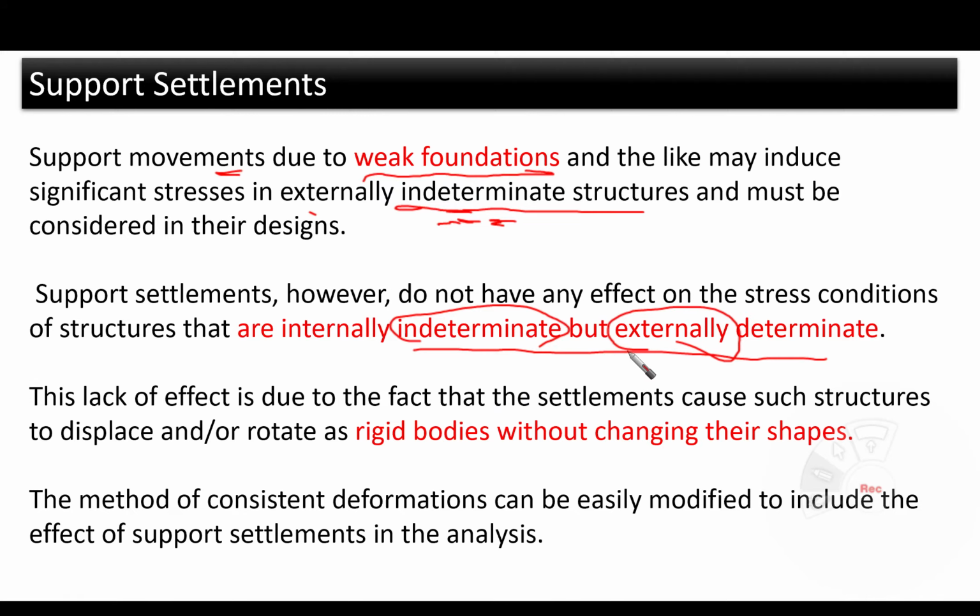We are concerned only with externally indeterminate structures, because in this case additional stresses are going to develop. So our main point is that our structure should be externally indeterminate in order to find some effect from the support settlements.